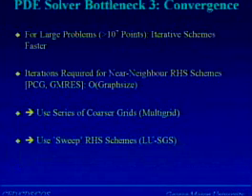The third one was convergence. As we grew the models, we found out that convergence was getting rather slow. Right? And we know that once we go beyond 10 million degrees of freedom, any iterative solver will beat any direct solver. What we found out was that the iterations required for near-neighbor right-hand side schemes like conjugate gradient or GMRes were of the order of the graph size. Well, the graph size was increasing tremendously, and if you think about an artery, the graph size can go into the thousands. So the number of iterations that you require just grows linearly.